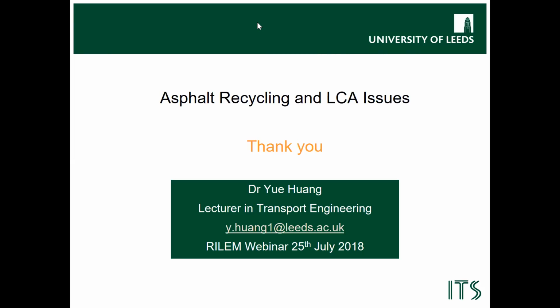Dr. Huang, I have a question. Nowadays, most of the current impact analysis of pavement LCA is not thorough enough. Usually the results of assessment show a list of pollutants data rather than the impact they cause, such as converting CO2 emissions into an index to describe the greenhouse effect. What do you think is the cause of this situation, or why do you think people are using LCA in that direction rather than showing the actual pollutants data and the impact?